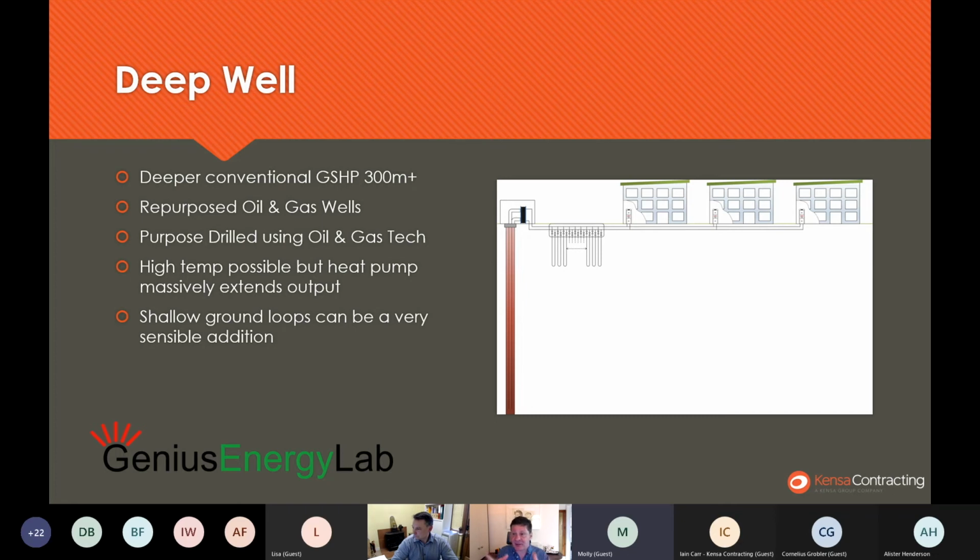The deeper you go, the hotter it gets. We don't see much of an effect at the 200-300 meters we normally drill at, but at 3, 4, 5 kilometers, you can be up to 160, 170 degrees in the UK. The cost of that well is high, obviously, but you're getting a very high enthalpy, useful energy source, so we're exploring all the economics of that at the moment.